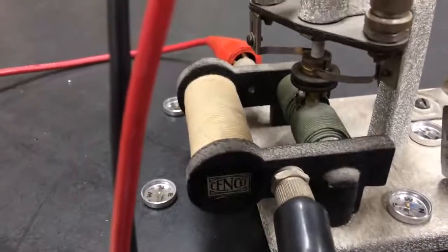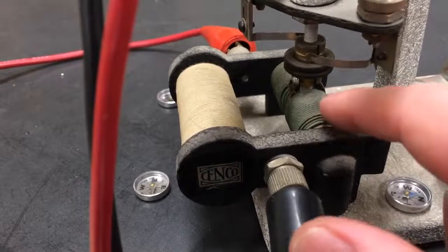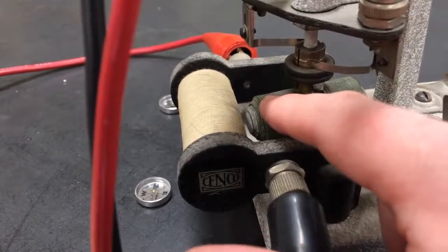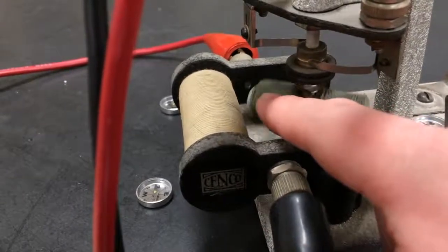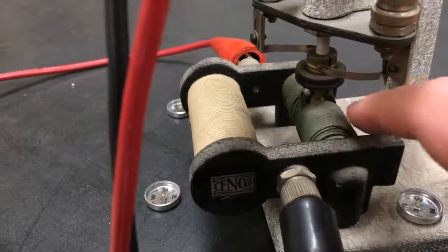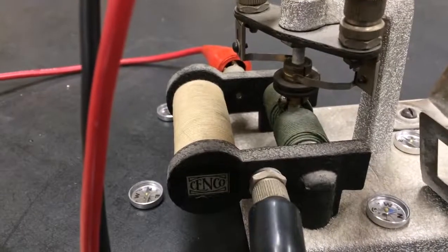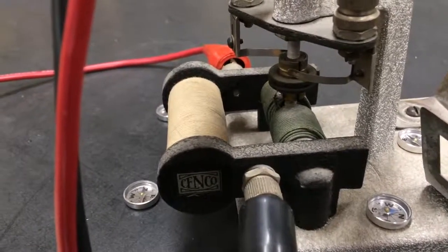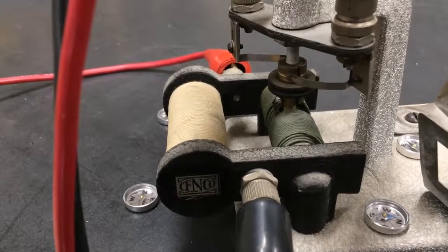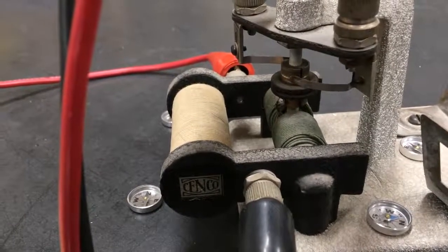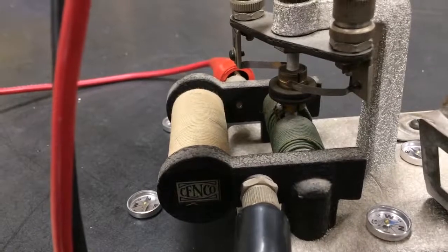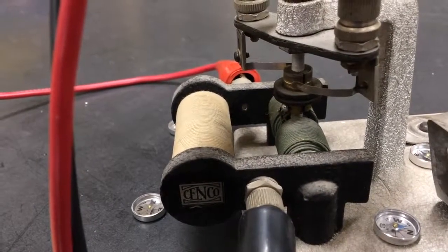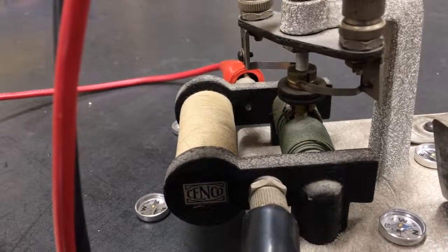Well, that's great until it turns 90 degrees. Then the opposite arguments are going to apply, and it's going to get pushed back the other way. And it wouldn't go anywhere. It would just get pushed back and forth. So in the simpler motor you saw, the one from SciToys, we solved this problem by just having the motor be off half the time. The rotating part only made contact with its power supply 50% of the time because I only scratched off the insulation on half the wire.